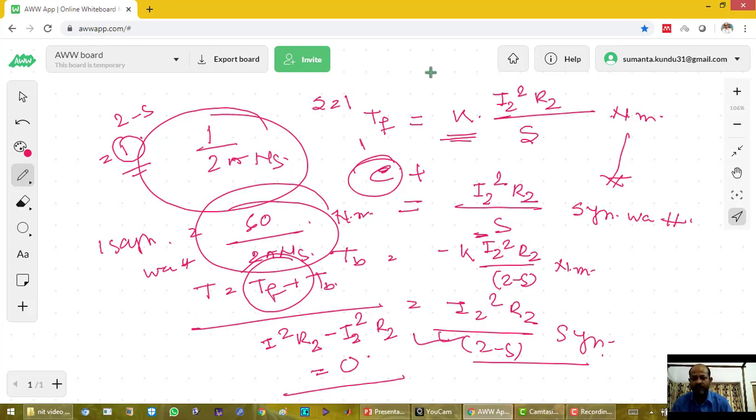This capacitor is connected with the starting winding or auxiliary winding, and when the motor has got its initial inertia to start, this centrifugal switch cuts the starting winding, rather the capacitor, from the circuit, and the motor will automatically start rotating.